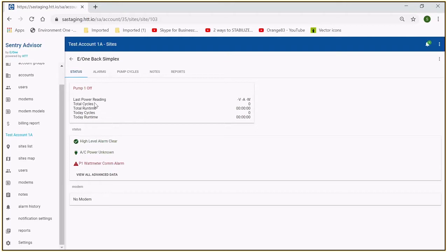If it's a single family residential, we expect 20 to 30 cycles a day. If this thing's been in a week and already broke 500 cycles cumulatively, that's probably something that you guys would want to check out, make a proactive phone call to the customer for, and figure out what they have that is throwing the pump into runs more frequently than we were expecting. Water softeners, sump pumps, a crack in the tank, infiltration through the tank lid itself, something that's causing the pump to cycle more frequently. And again, that's the power.